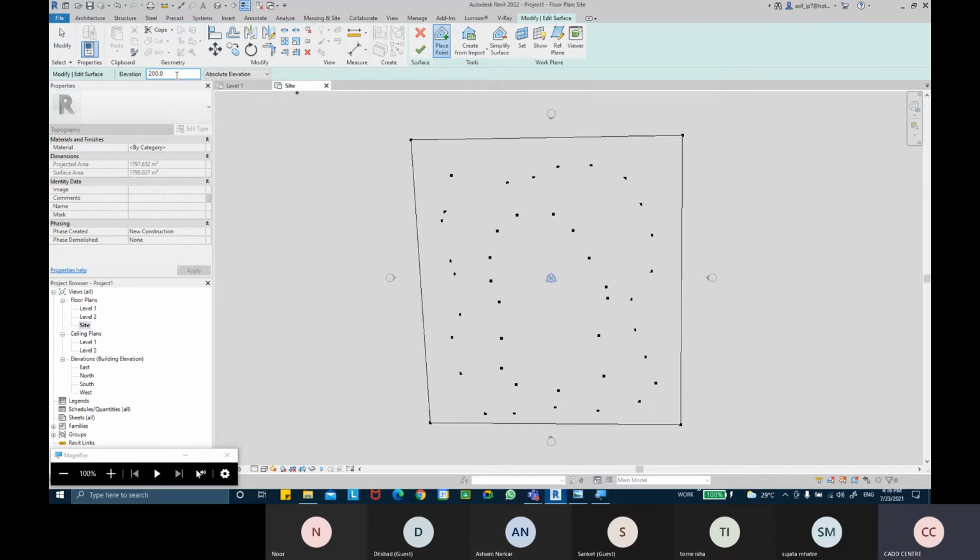So maybe from that level, I want only 50 mm to come down. I don't remember what my last point position was, so I can say relative, and then I can put it in. I want only 50 mm down relative to that surface. So I say negative 50, not positive. If I go positive, it will go upwards, right? So I'm going to put negative 50 relative to the surface, which means from whatever my last coordinate is, it will come 50 mm more down.